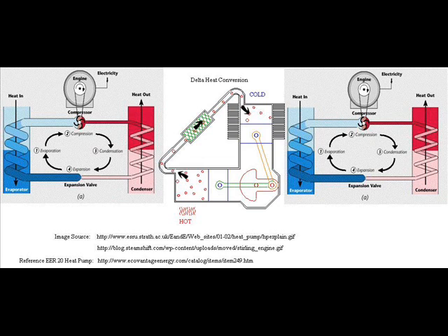In order for that system to work, the efficiency of the heat energy temperature difference conversion to electrical energy step of the process must be greater than the inverse of the COP. In our case, a 5.8 means that that conversion must be greater than about 17% efficiency.